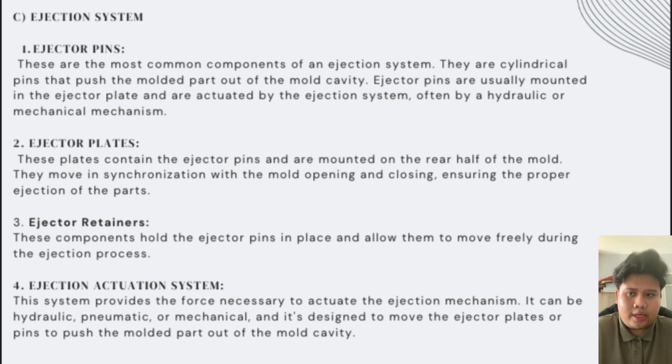4 is ejection actuation system. This system provides the force necessary to actuate the ejection mechanism. It can be hydraulic, pneumatic, or mechanical, and is designed to move the ejector plates or pins to push the molded part out of the mold cavity.